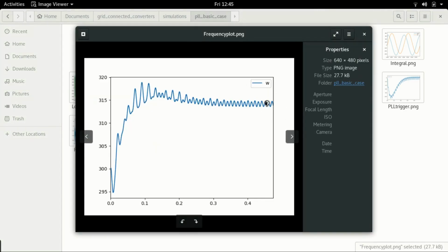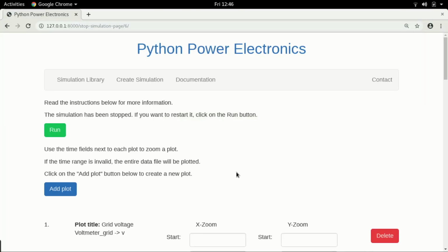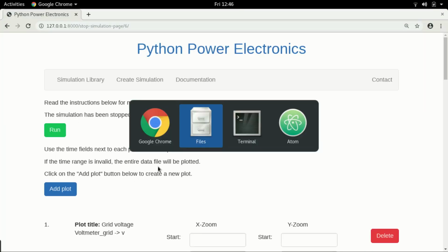This smooth waveform was comparable or even better than the waveform that we got when we had no integration offset, or rather when we integrated we got no integration offset because we chose the grid voltage to be a pure cosine waveform. So now we'll go to the next level and change the grid frequency.